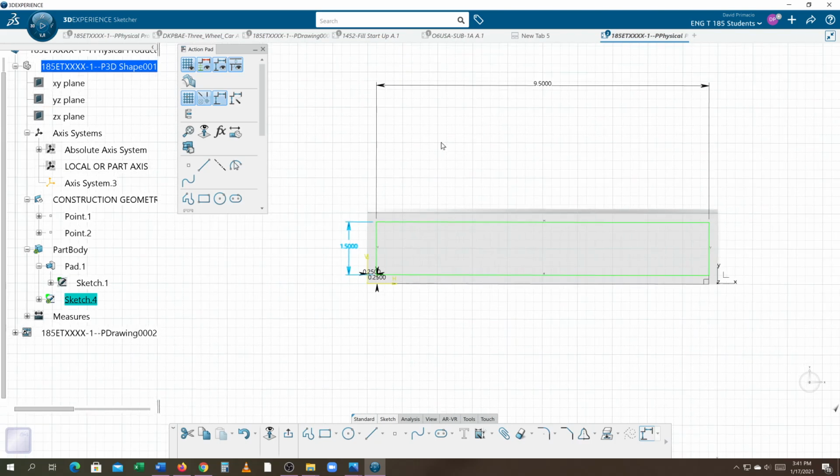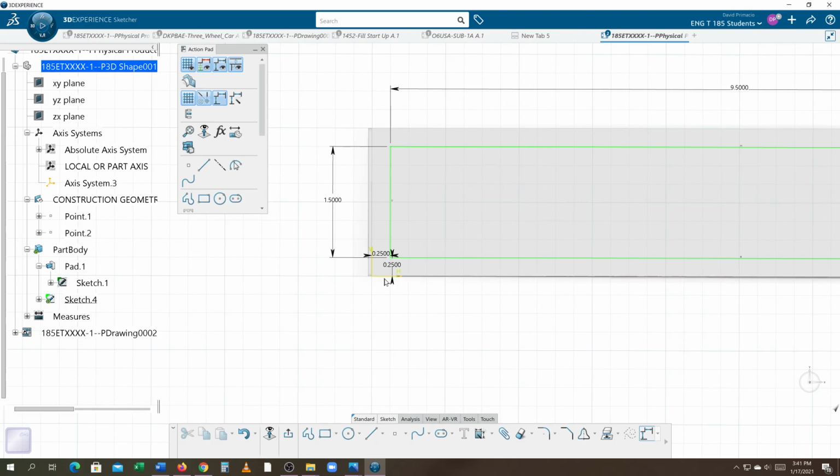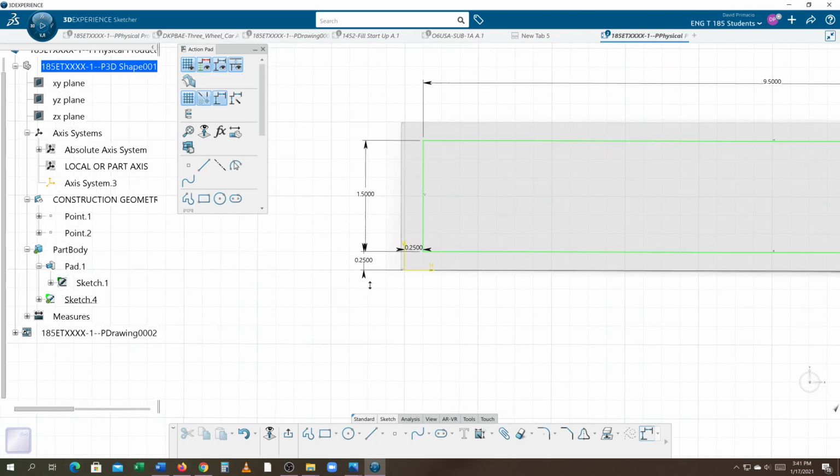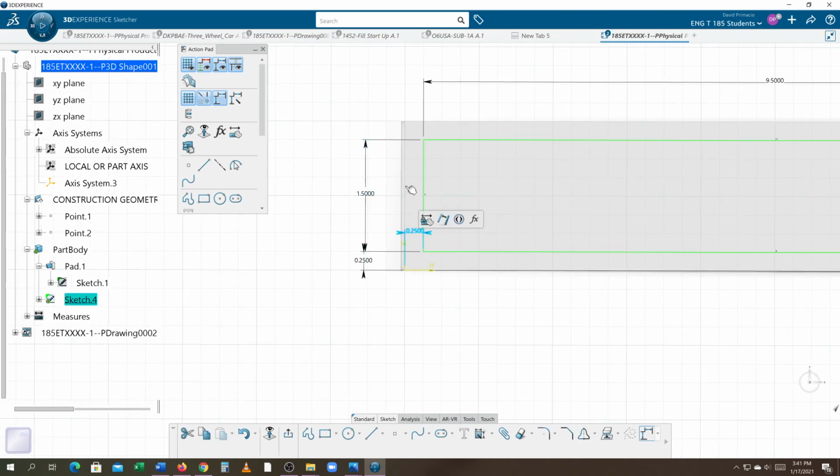Okay, and technically these should be brought down to 3/8 to half inch off the part. So I'll just approximate that. And this view here should be chained up with, or this constraint here should be chained up with this one. Okay, so you should line up these nice and pretty, get them all lined up. And I actually would have the number on the outside. Okay, I would bring this number on the outside.